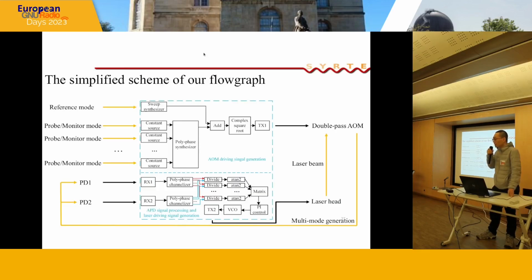Just a word: indeed there is some digitization noise and noise in calculation and all that, but the important point is that there is also some physical noise coming from shot noise of the optical detection, and we qualified all that to show that the optical shot noise, which is a fundamental noise you can get physically, is significantly higher than all these digitization noises. And actually, I think this last slide really emphasizes the beauty of software-defined radio, where in the analog way you would be hard-pressed to do anything more than a summation in your operational amplifier, where here you can feed everything in a matrix, you can invert your matrix, you've got the flexibility of software processing as opposed to the analog approach. Yes. Thank you very much.